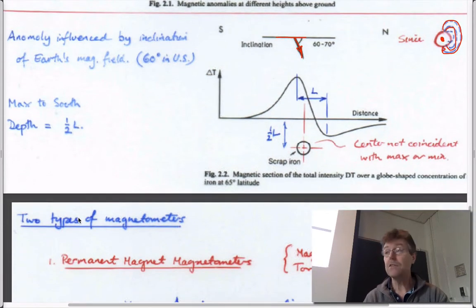It's really only useful if the targets are magnetic. It won't find holes. It won't find other things in the subsurface. So if you think that the contamination has come from something like that, then it's a decent mechanism to use. The other thing is that it is quantitative as well, not just qualitative: you can invert the signal that you get by going across the surface to figure out exactly what the feature is in the subsurface.